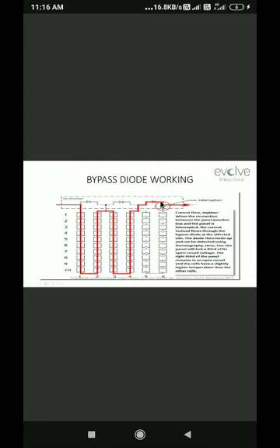Here there is one more small thing to add. There is an interruption. You can say there is no bus bar connectivity between these points. See, there is a bus bar connectivity here, but here there is no bus bar connectivity. The bus bar is damaged. If the bus bar is damaged, you are making a 1000 volt string.